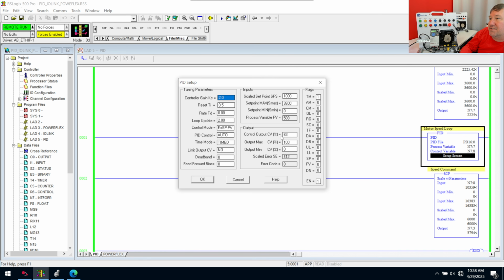Let's drop that to about 2. And then we're looking at this number now. XT, not oscillating horribly. Why did I put this at 1,000? I should have put it in a number that we didn't have to scream on the mic. So in fact, right now, I am going to drop this down to 500. So I'm not screaming at you. Okay, so you see it zigzagging a little bit now. It went down to 498, going up to 477.